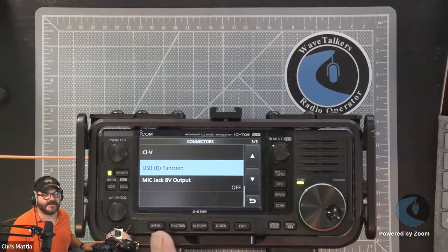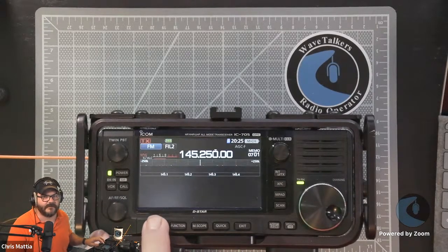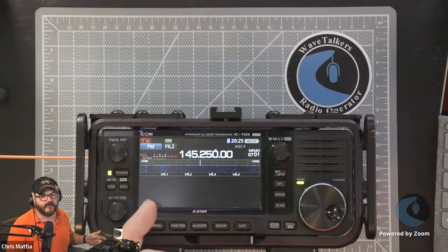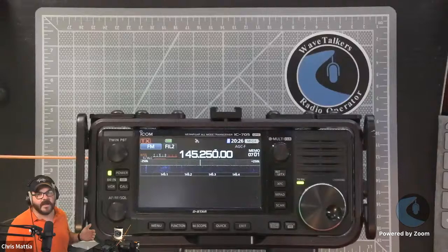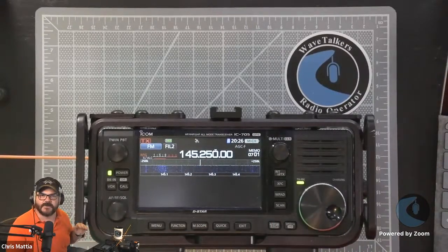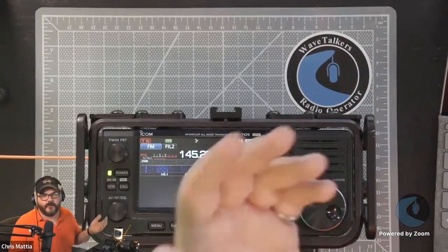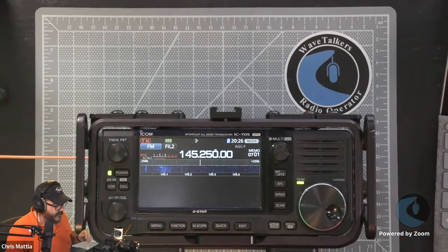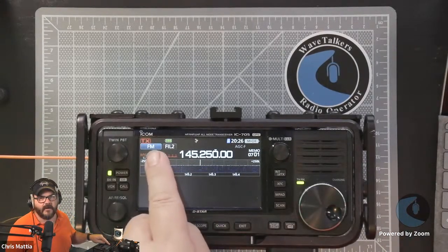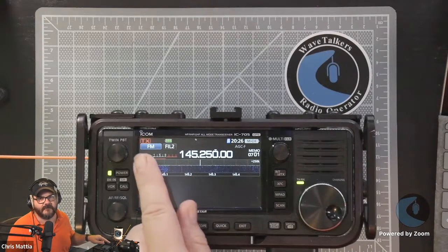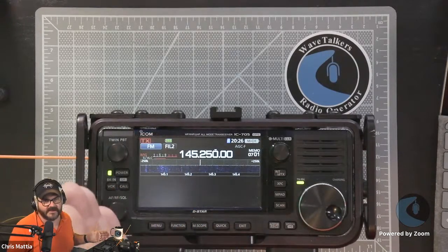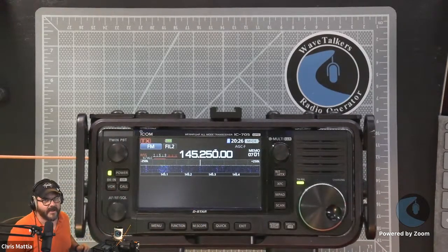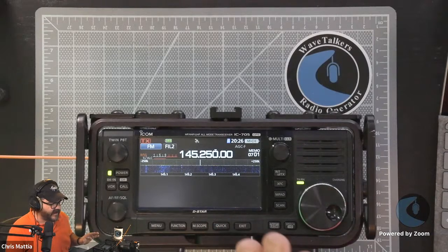And that's most of the settings that you've got to make sure that you've got on the 705. Obviously, you want to make sure that if you're doing VHF, UHF, you're just in the FM mode. If you're on HF, you're going to be doing upper sideband, especially if you change over to, say, the 40-meter band or any of the lower bands. Keep an eye on your transmit up here, making sure that you're always in the right mode. If you're doing VHF, UHF, make sure it sets it back to FM. And if you're on any of the HF bands, make sure it's always in upper sideband. Those are kind of the settings on the radio itself.